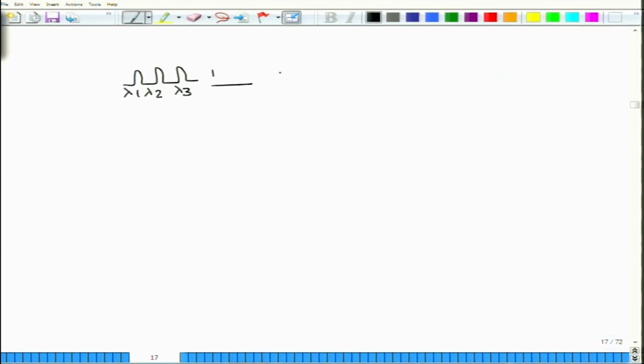Circulator is fine, so the way to put that one would be slightly different. So I will actually have a circulator here, with 1, 2 and 3 ports. Okay. Now here I will have a filter, but I don't have any filter. I have a very specific filter which I will call a Fiber-Bragg grating. Okay. So this is a grating which is created out of an optical fiber itself, and this specific grating is called a Fiber-Bragg grating, and this will act as a filter or a selective component.